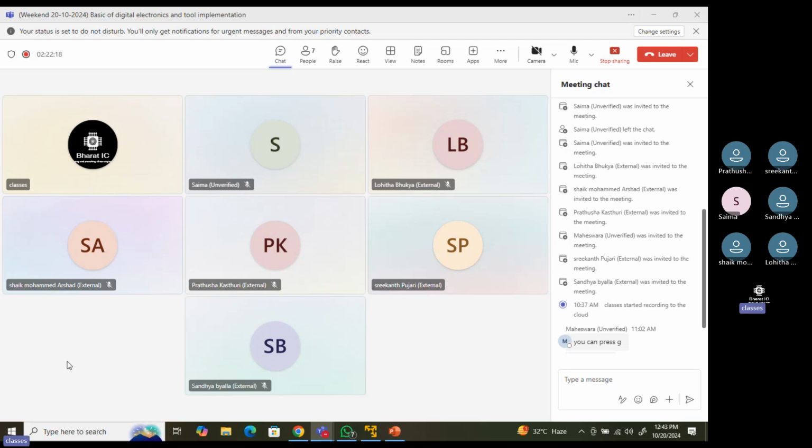No, suppose one M2 track is passing, okay, you have done one routing for the M2 track. Now assume that M2 is a signal A, and there is a signal B also which will cross that M2. To cross that M2 you cannot route with M2 only. M2 will get shorted.